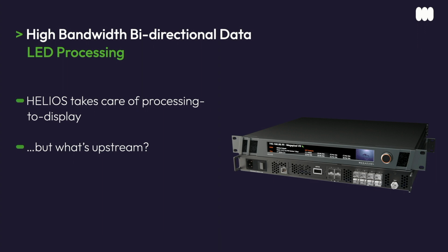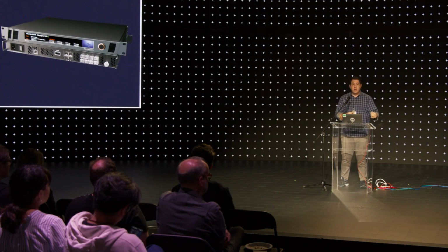Your laptop identifies itself and says, I'm a Mac laptop, there's Safari being used, and I'm browsing, and I'm requesting something from YouTube, and everything happens automatically. We do the same thing. The tiles actually identify themselves on the network. Helios reads all that metadata and says, oh, I understand you're an XYZ brand tile, you have RGB pixels, you're this resolution, you have this driver type. I'm going to send you data in the right way and send you the right configurations so that you produce the correct color, the correct tone mapping, all of these things.